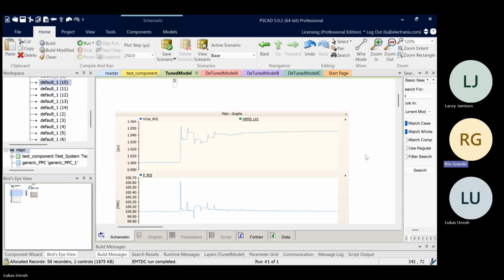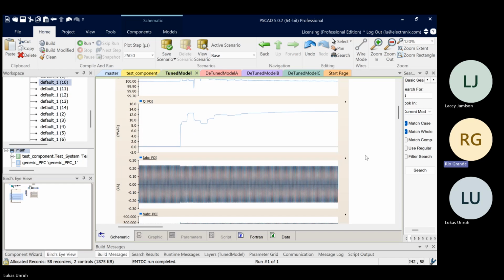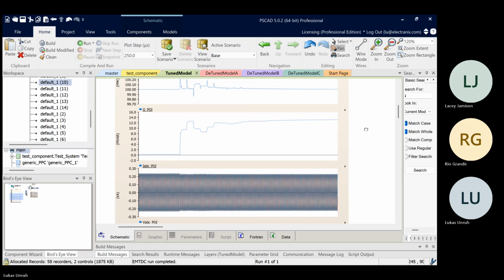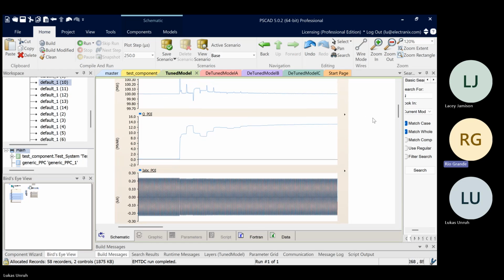voltage response in a weak system. It's not abnormal to see something like that. And this is due to plant controller delays and cycling time and sampling times and things like that. And again, this is a generic model, so I put these in here on purpose, but I've seen this come out of real plant controller models, things that look very similar to this.